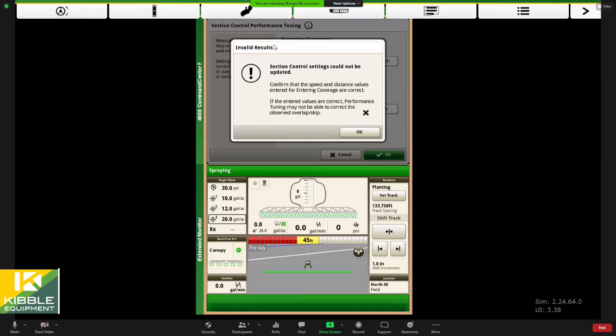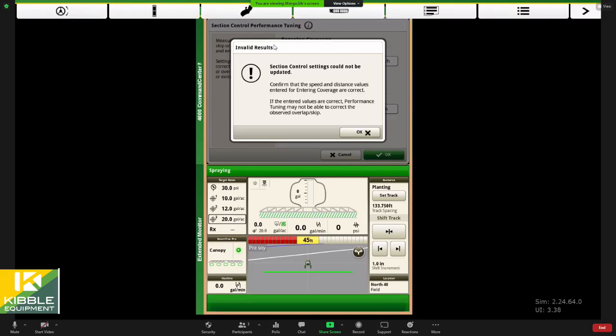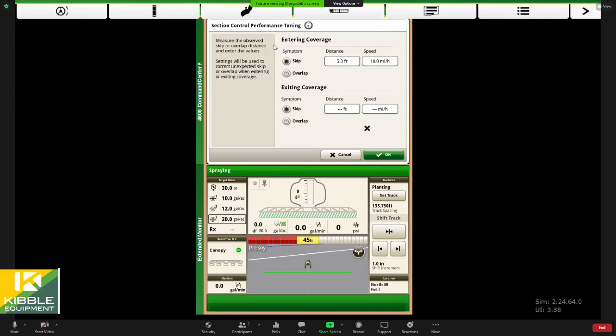But if we are getting information like this, where it says invalid and it could not be updated, either we've tuned it all the way down to where we can't tune anymore, or potentially you've got a measurement that's off in that scenario. So there's just no more time to adjust, right? Or delay to adjust. And that probably might be too because of my default mechanical delays.